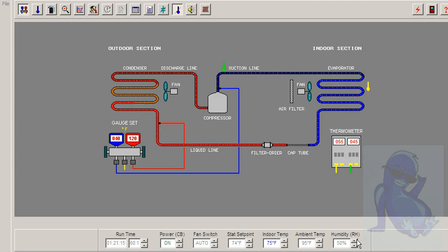So I think that's a pretty good review, just to get pressures and temperatures in your mind of a normal running system. After this, let's create some faults in the system. You'll be going into a service call and we'll be simulating a problem. The problem might be a variety of things that you would normally see in a system, and let's see what things look like in a system that is not running properly.